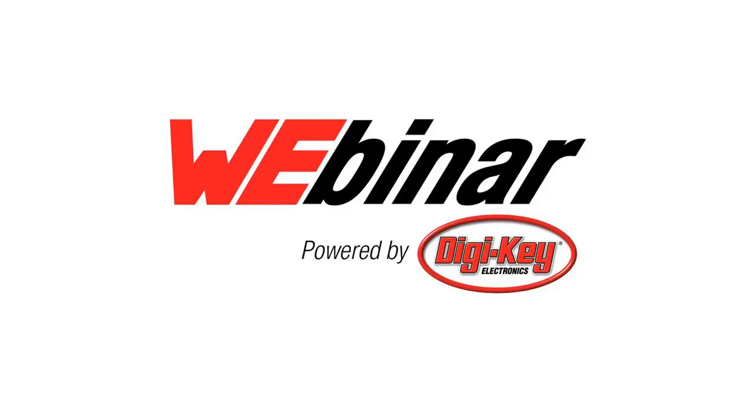However, not the branded Quick Charge version, which I guess is Qualcomm specific. I haven't necessarily been involved personally with a lot of those designs. More often than not, the ST-USB 4500L or the 4500 is integrated with a device of some kind that is specifically looking for a certain power contract to be able to charge its battery. And those devices have power profiles programmed into NVRAM, and versus the source side, during the negotiation they're going to try and choose the highest power profile that both sides support.